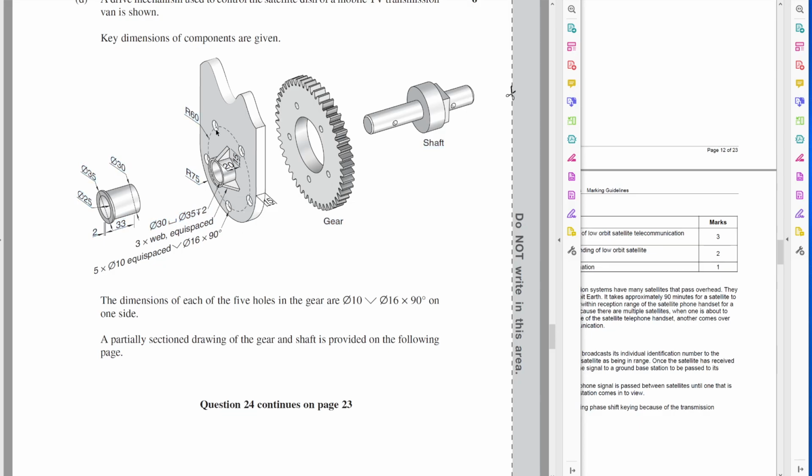But the idea here is that we're only going to section. Are there 3 of these? There's 5 of these stiffeners. No, 3. Okay, so even though there's 3 stiffeners, we're going to draw them as though there's 2. And even though there's 5 of these holes, we're going to draw them as though there's 2. And we're going to show them both happening where we're cutting through the section. That's just common practice because, believe it or not, it's more confusing if we don't do that.